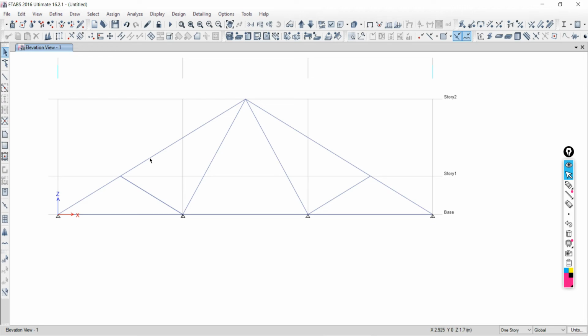Now let's talk about, first we have to complete the modeling. First understand the break command. See, I have completely modeled from this point to this point. At every intersection point, your element is going to be broken and divided. In case of truss, it will not be like that, where one element rests and another element's end lands over the mid portion of any element. It will not happen. Always two elements will be joined at their ends only.